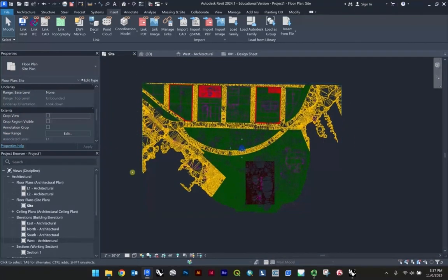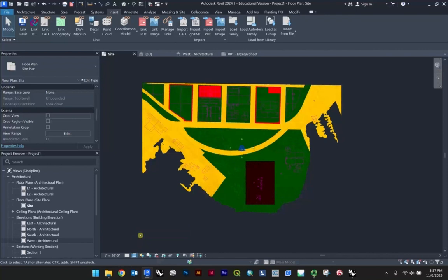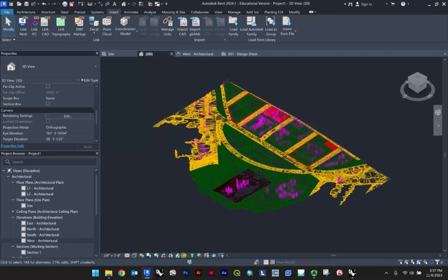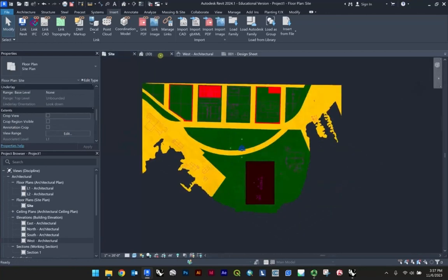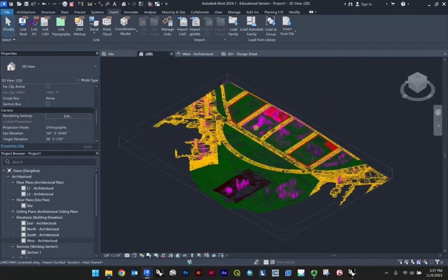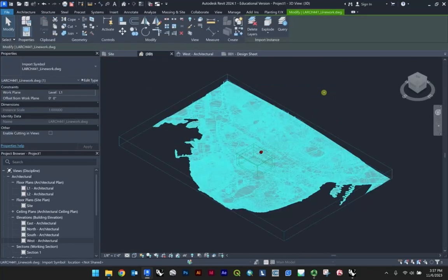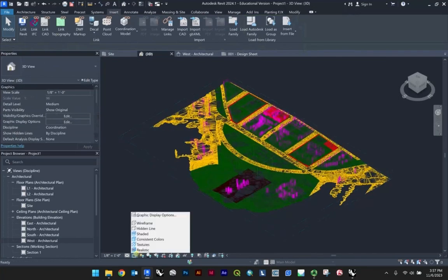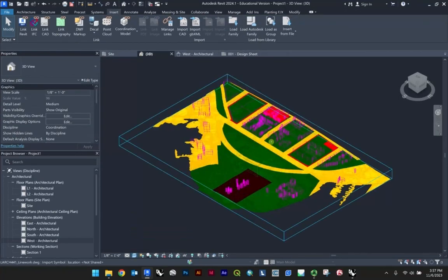The other thing that you can start to play around with is these views, or the visual styles. So if I click on this, you can go to something like shaded, which is maybe a little bit more traditional to what you're used to. Similarly, what you'll see now is it doesn't change view to view. This view setting is not going to translate over. So we do have to update it here as well. And we would just do that in the exact same way. Shaded, there we go.